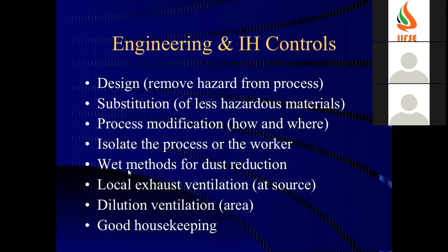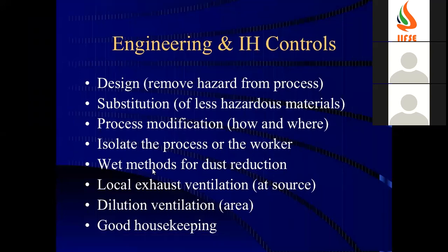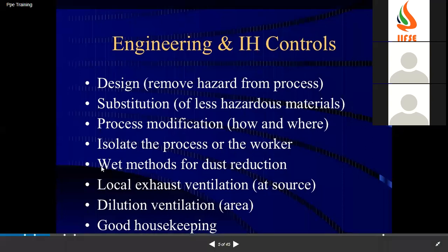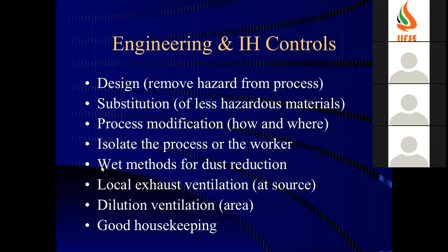So when companies deal with coal, iron ore and all, during summer, this peak time, they get dry and they fly all over the place. So to reduce that, we use a wet method. Wet method is sprinkling or watering the area or spraying water by different means.